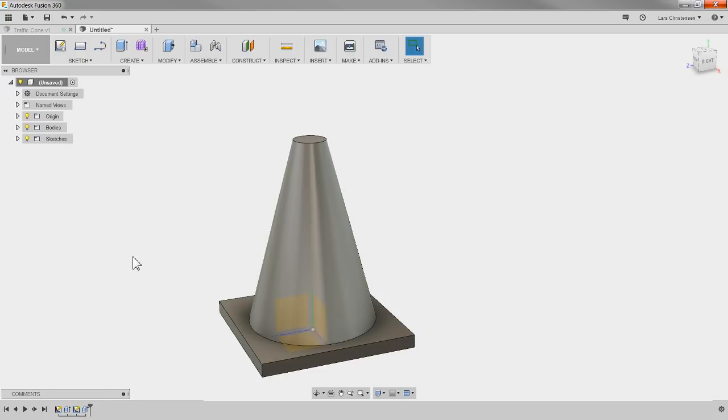If I decide to start another sketch up on this level that went in another direction, when I move this sketch, that thing up there is going to be attached to that face and want to go with it. So yes, you can, but be a little bit careful with it. That's just the nature of it. But yes, you can. Good question.